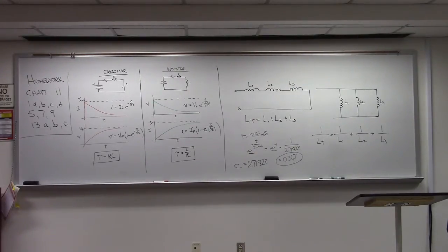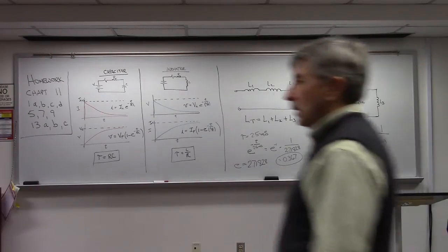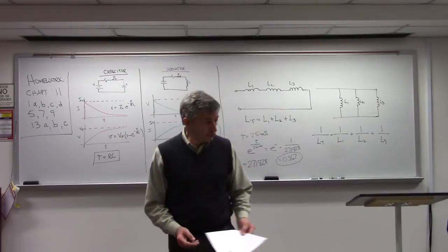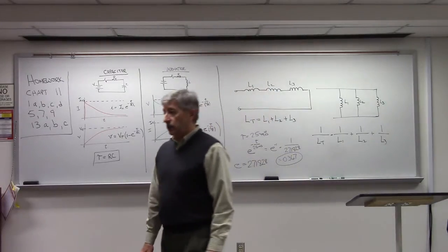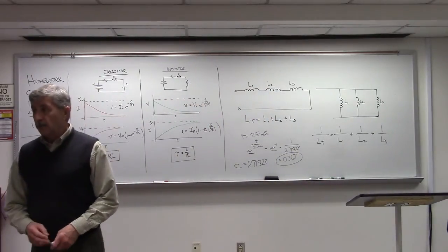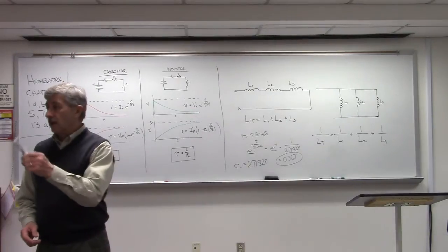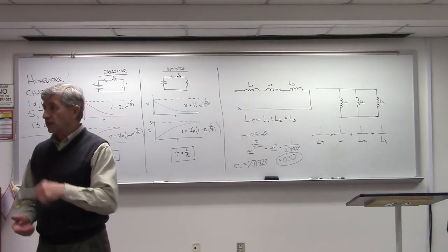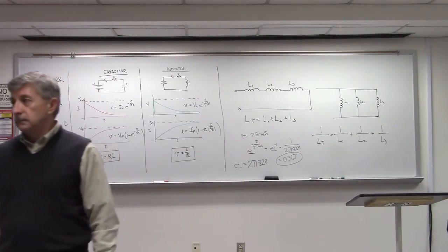I'm getting fancy on these Multisim circuits. You can see when you get your paper that I have the wires colored with different colors. If you right click on a wire, you can change the color of the wire. That might help you trace out your circuit better. Whatever color you make the wire, that's the color of the waveform on the screen. Okay?